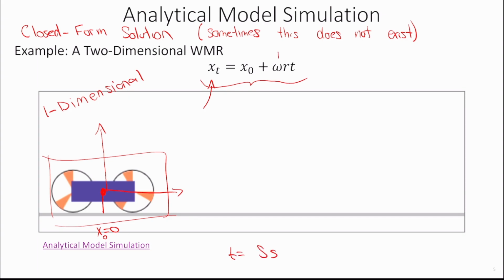Well, if we assume that our wheel rotates, or both wheels rotate, at a specific fixed angular velocity of omega, and we know the radius of the wheels, and we know how long we want it to run, so for example that's 5 seconds in this scenario, and on our robots those are about 7 centimeters, and we get to set this.